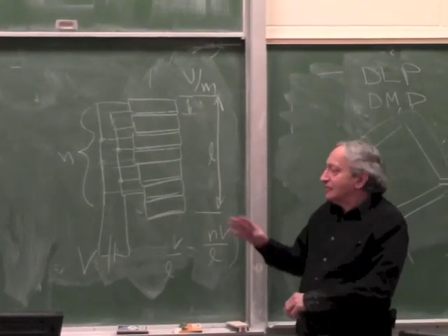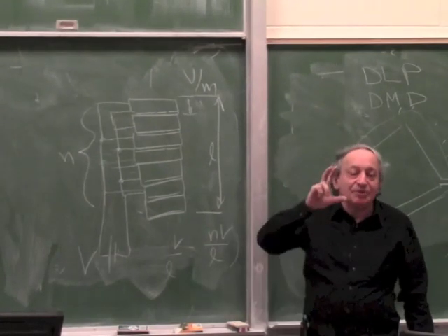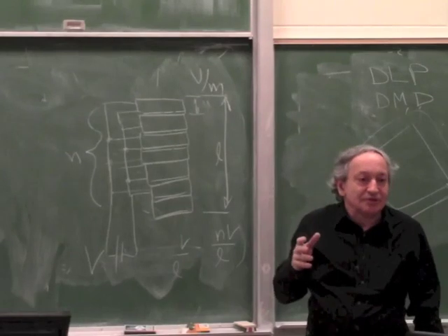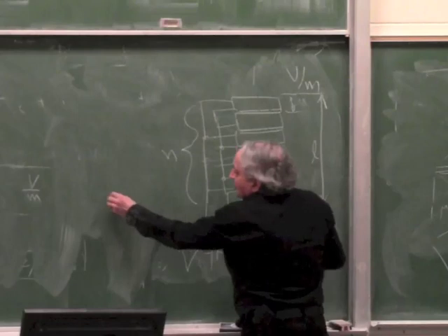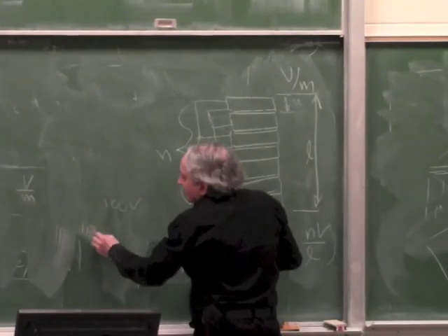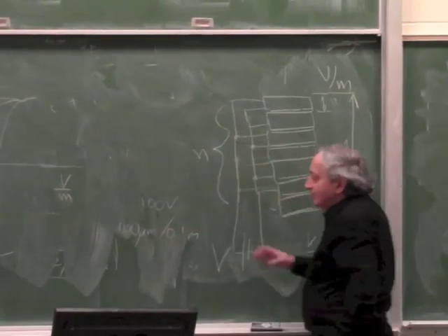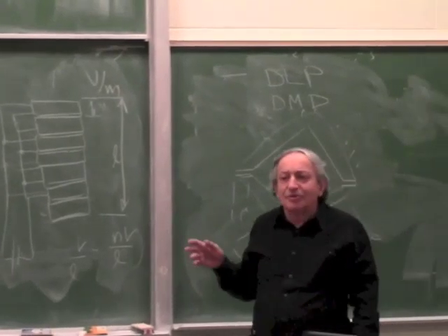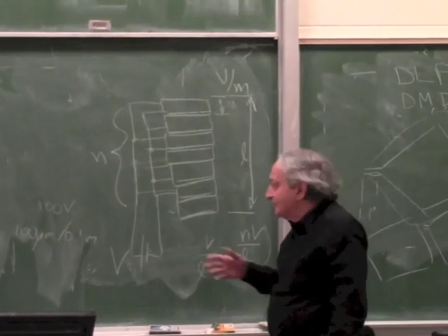Okay, so this solves the first problem. Now, if you have a stack about 10 centimeters long, you can move 100 micron with a reasonable voltage. Take a good number of today's stacks like this: if you give it 100 volts, you can move maybe 100 micron over a 0.1 meter stack. It's a typical performance number. Okay? It's comparable to magnetostriction. If you take a good magnetostrictive material, it's comparable.